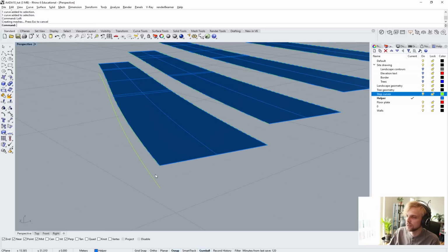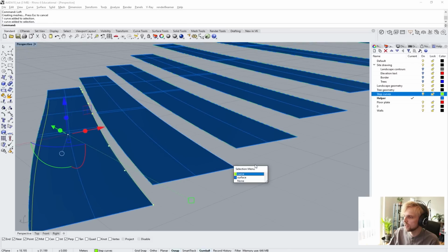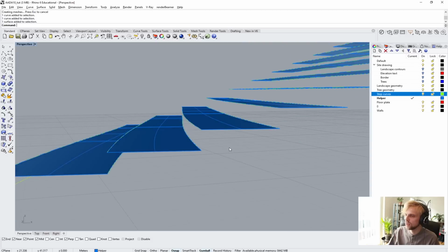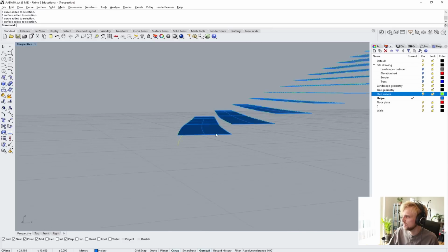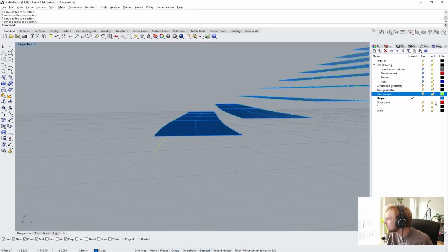And then I do it vertically, right? But to do it vertically, actually, all I need to do is just select all of the ones that are in the bottom. So this guy, hello, this guy. Let me go to step curves tool, make sure that it's the active one, and lock the helper tool so that I don't accidentally select my surfaces anymore.